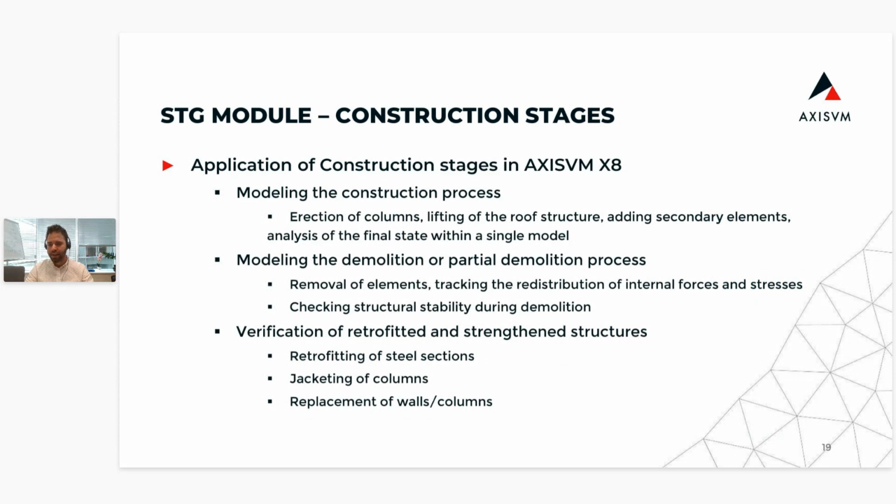We can model the demolition of the structure or partial demolition process of the structure. So we can remove elements and we can track the redistribution of internal forces and stresses due to these removals. And in these stages, we can check the structural stability of the structure during this demolition process.